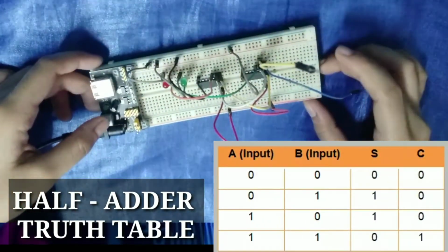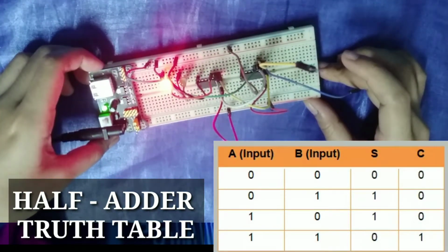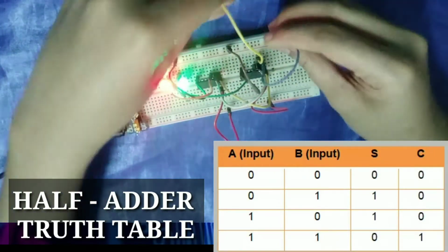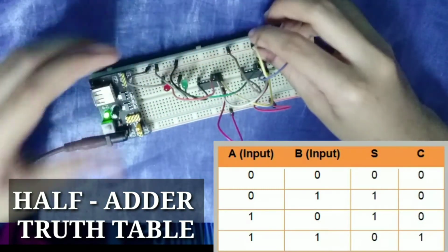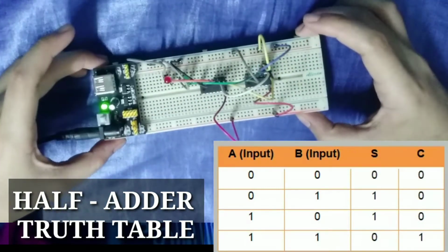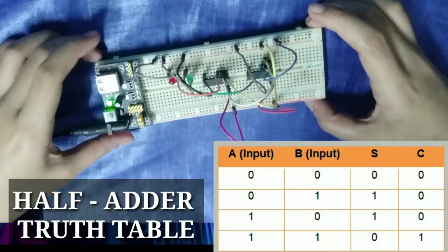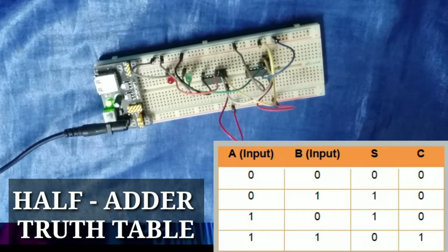Now for our output, let's turn on our voltage supply. If both the A and B, or the X and Y input, are connected to the ground or 0, as you can see, the output for the sum and the carry, or the red and green LED, is 0, meaning it does not turn on.